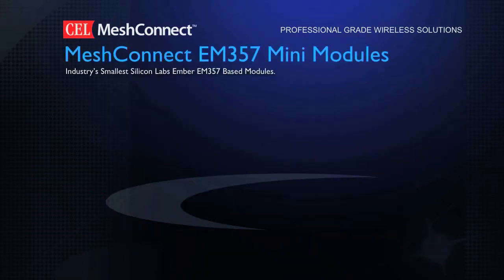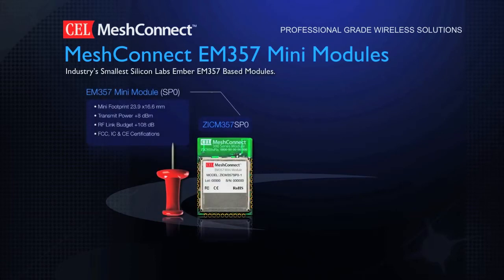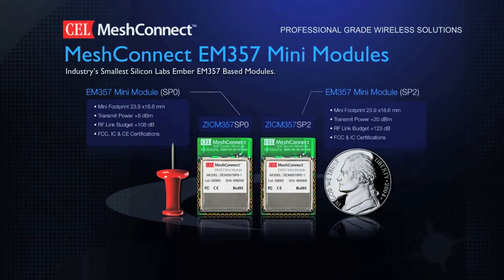In this demo, we will showcase CEL's MeshConnect EM357 mini modules, the industry's smallest Silicon Labs Ember EM357 based modules, with a mini footprint of 23.9 mm by 16.6 mm. The MeshConnect mini modules come in two flavors: SP0, a low output power solution with a transmit power of 8 dBm and an RF link budget of 108 dB. This module is FCC, IC, and CE certified. SP2 is a high output power solution with a transmit power of 20 dBm and an RF link budget of 123 dB. This module is FCC and IC certified.